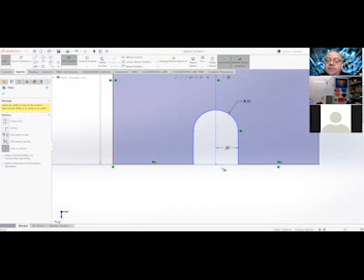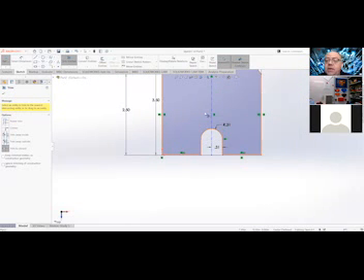I'm going to take that. And now, if these stay blue, I'm okay, because I know my numbers are right. If you're really worried about them not being black, you can add more constraints, but I really don't need them because I do know the radius based off this side, and so I'm good. If you want, you can do a diameter, but you're good.